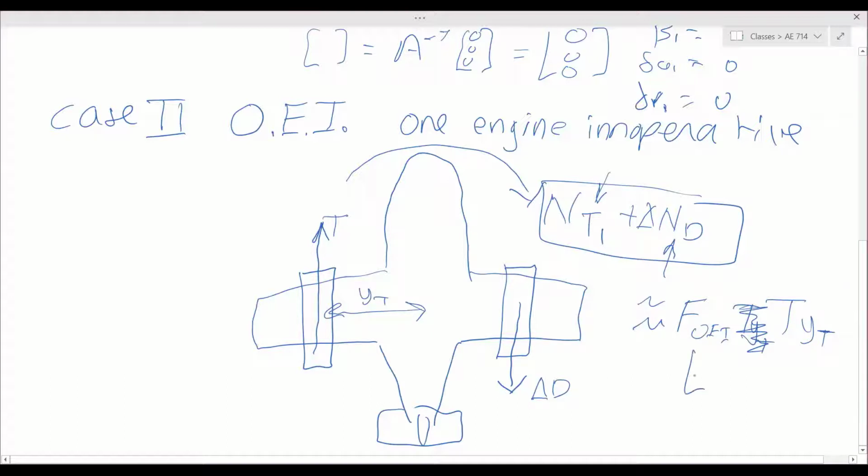And then he has tables for this N_E, where you look up if you have a turbofan engine, it gives you a number. If you have a prop jet, it gives you a number. If you have a piston engine, so you just look through those tables and you get a number, and that allows you to at least size things for a preliminary design.